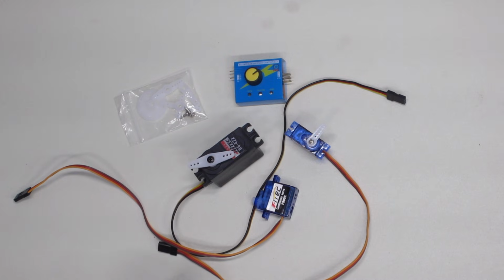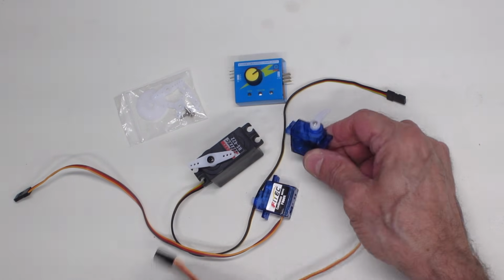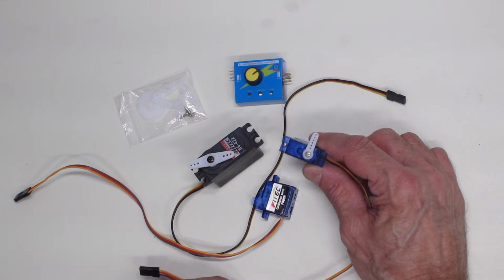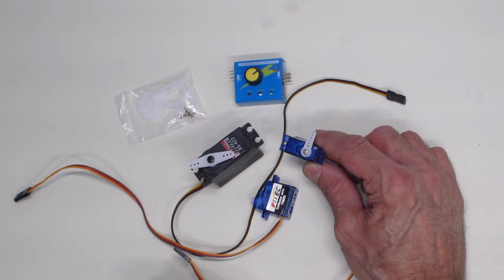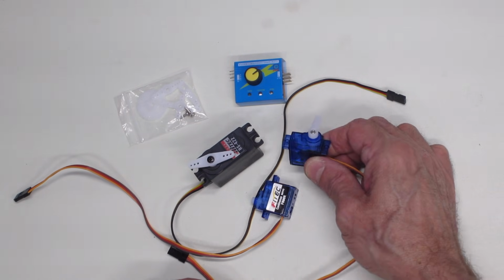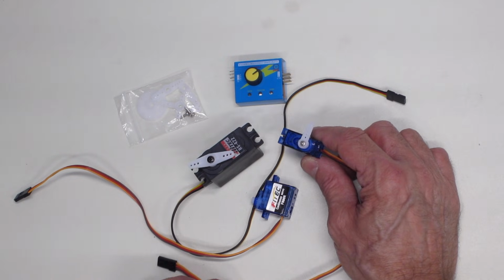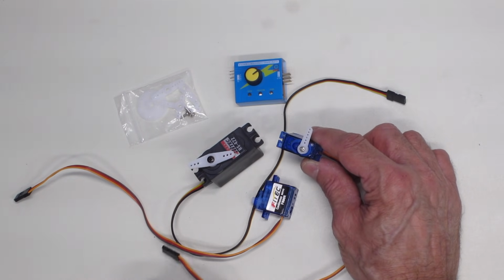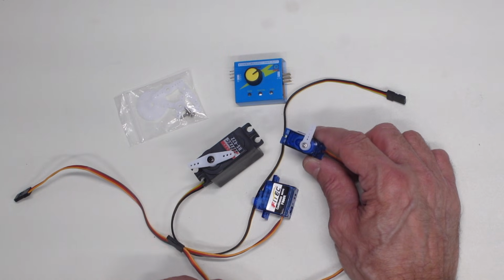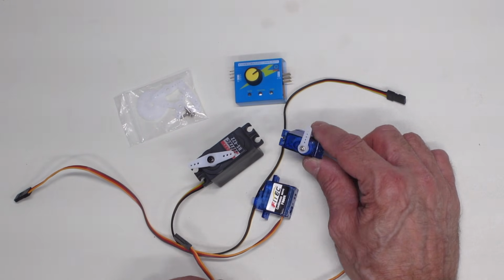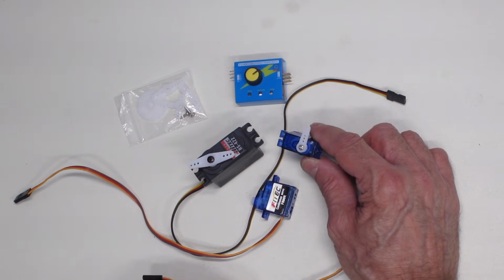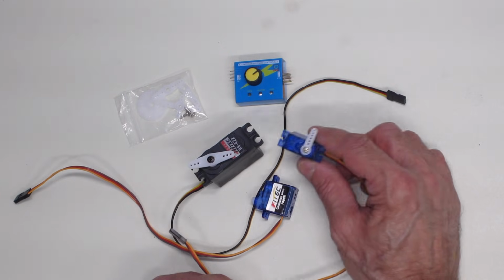And so here's an example of some servo motors that you could use in these experiments. Now this one over here is the most common type of servo you're going to find for hobbyists. It's called an SG90, and it's available just about everywhere on eBay, on Amazon, and probably your local electronics store as well. Now there also is an MG90, which is functionally identical but uses metal gears instead of the plastic ones used on the SG90. So if you have something that is going to have a risk of having some load applied against it, you're probably better off using the MG90.